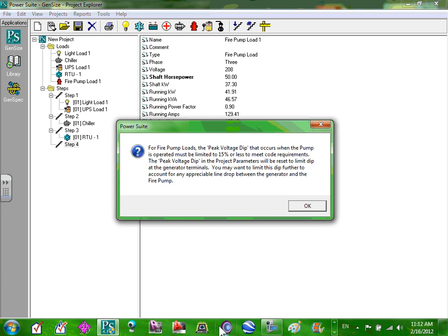And if we've sized it with the biggest load last, and we're still starting and running, we've done a good job. And we'll go back and look at the very end and see, once everything's up and running, I like to size it at around 70% of the generator set's capabilities. That does a couple of things. Customers, you ask them up front, are you planning on expansion? Like you mentioned earlier, we're going to put 50% more on this building later. We want to allow for that on day one, not when we're getting ready to do the expansion, which might be a year or two later. So if we've covered it up front, we've done a good job of engineering. Good question.